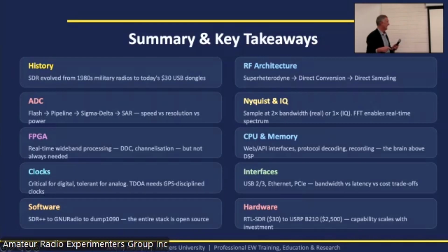The multi-bit input Sigma Delta, which instead of using 1 bit can use up to 3 or 4 bits, is able to get somewhere in the area of 18 to 24 bits of real data as its conversion. And it is all a part of a very complicated mathematical process, which would take a whole couple of lecture series just to talk about.